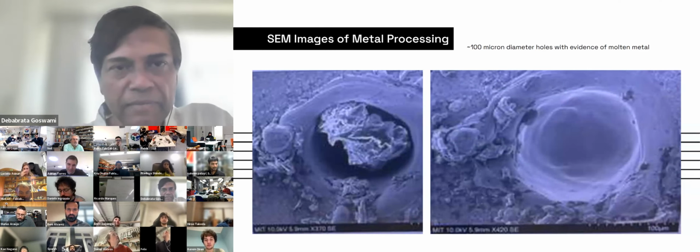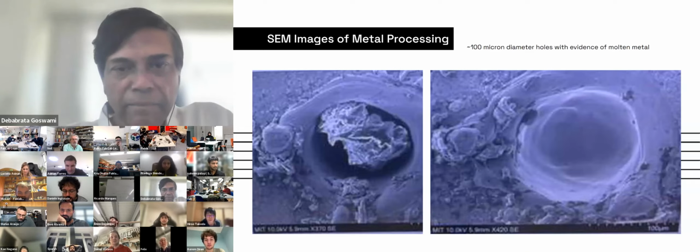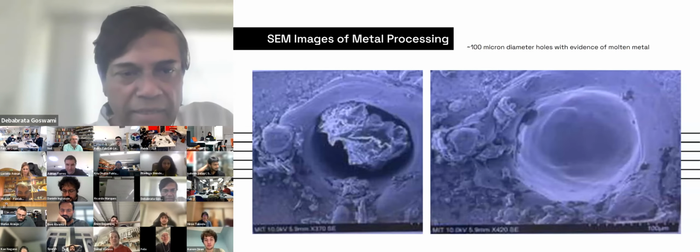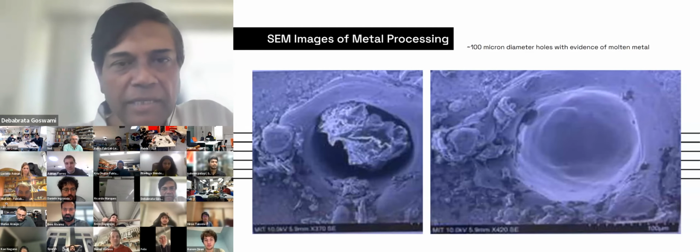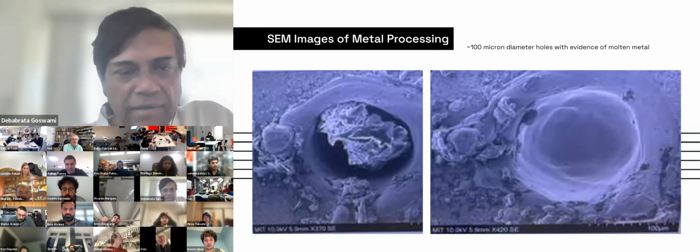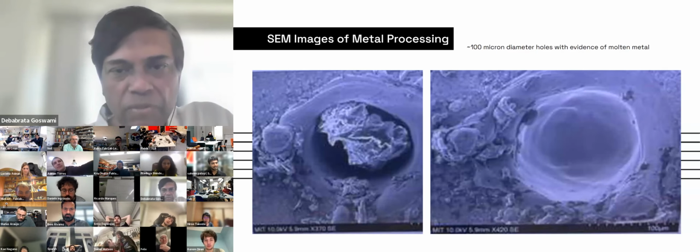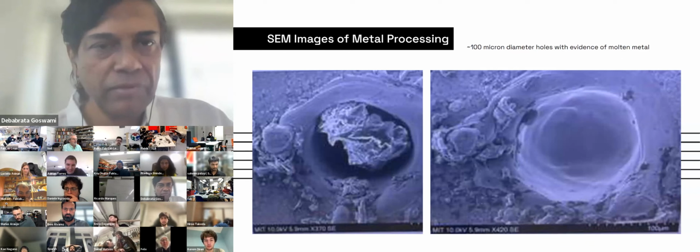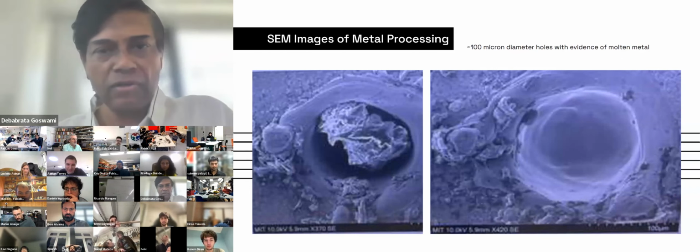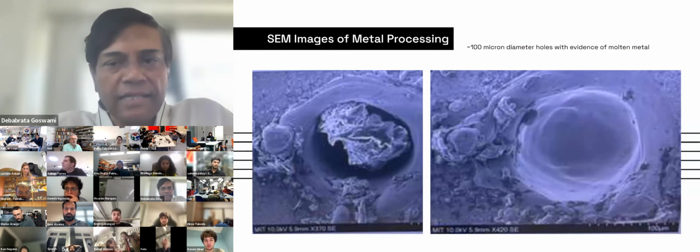But under this condition, the metal melts, and you can see the melt still remaining there and its features moving out of the hole, and you can kind of estimate how these are. So these cavities that are formed, which are not through holes, before making the through holes, this just one shot at a time, are about 100 to 110 micron size, depending on the wavelength. So we have used this IR radiation, so it cannot go smaller than that. Next slide.